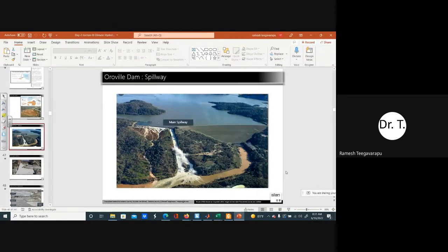But every part of the operation and structural stability has to be considered based on climate change or even climate variability. For example, right now we are in a kind of mild El Nino, so a seasonal forecast for the next 3 months has to be done to see how much water we are expecting, and whether we are expecting too much or too little. Depending upon that, you need to modify your operations.